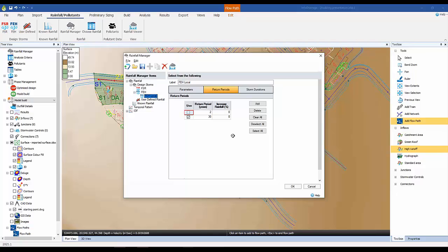But in there it describes how it must pass two tests. The first test is a no surcharge test, and depending on your catchment and where it is, typically it's going to be about a 1 in 1 year or 1 in 2 year storm that it's going to have to pass. So I'm going to say 1 in 2 year in my example. So the idea is that during a 1 in 2 year storm we should get no surcharging in the catchment.